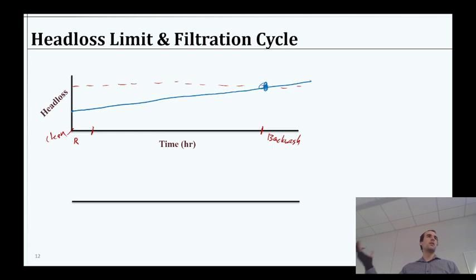It'll depend on, I guess, the amount of media, the type of media, and the type of particles you're dealing with, how dirty the water is. It'll depend on some things. If you have a very consistent source of water, maybe just that 36-hour timeline is always fine, right? Maybe if you have rainwater disturbing a lot of sediment upstream, maybe you have to change it a lot. You really have to monitor that turbidity. So it's going to depend on the practical situation.